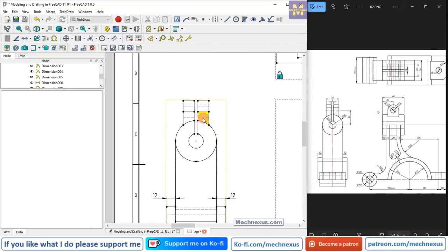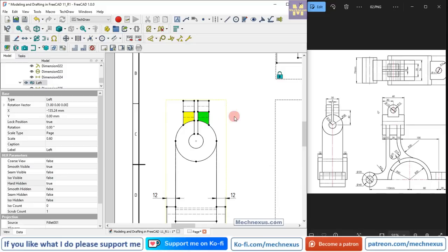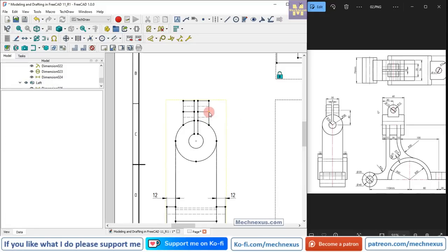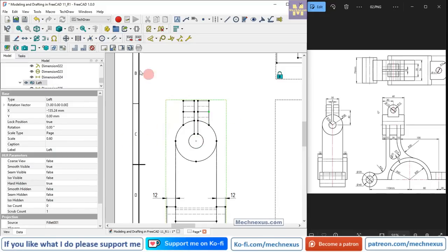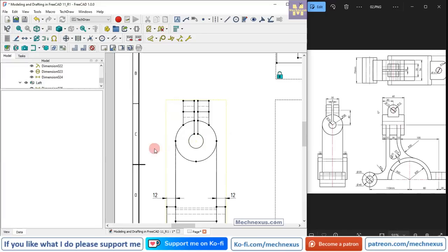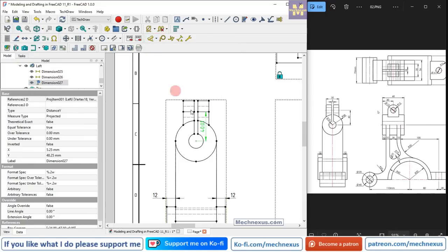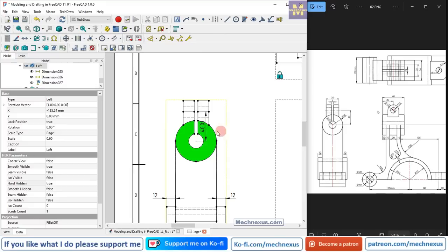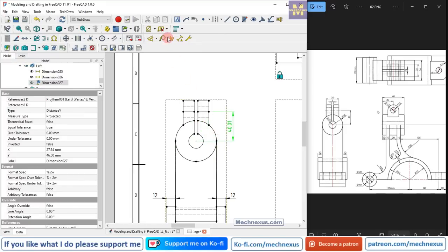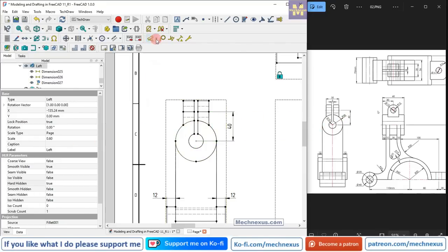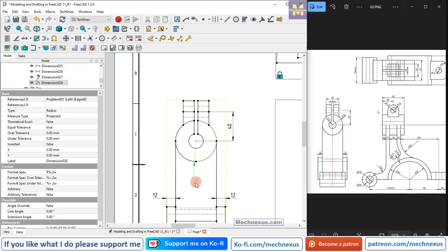And now I will insert a center line, with this chord point as a center, so I will select this and this center and this chord point, and add a vertical dimension of 40, and here I will decrease the decimal places to make it a round 40, and here it is R28, so I will select the radius and give it R28.